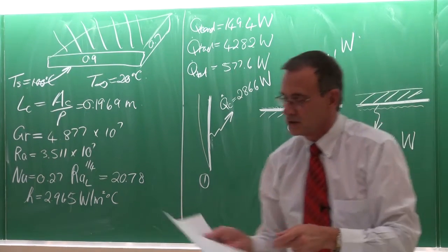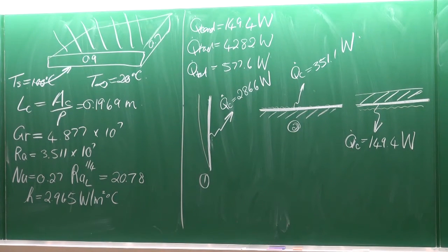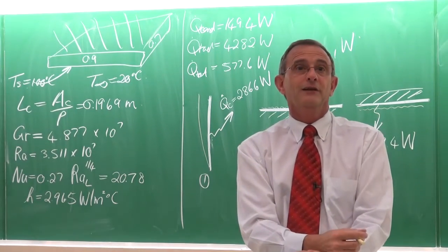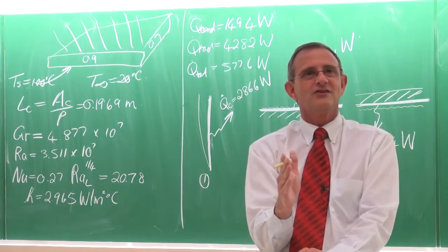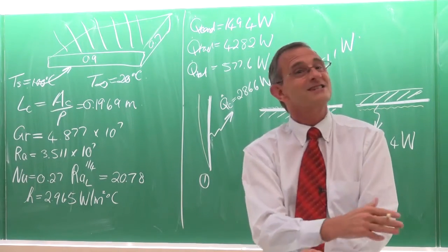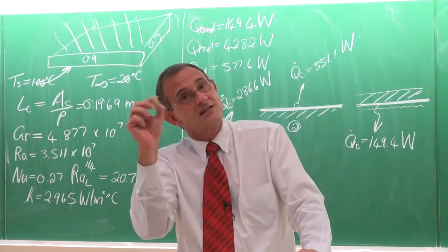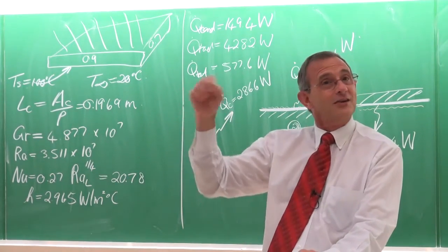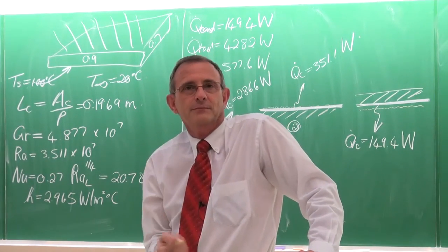Any questions, ladies and gentlemen? Yep. So what if the Rayleigh number is outside that range? Yes, if it's outside, then you have a problem, and then you have to go to the literature and get values. Some of you may end up in the exam just outside the range. Now you wonder, what do I do now? Because there's nothing else, you will have to say, I realize this is outside the range, and I realize most probably I've made a calculation error. So I know I shouldn't actually use it, but because there's nothing else, I'm going to use this correlation. Then it's fine.